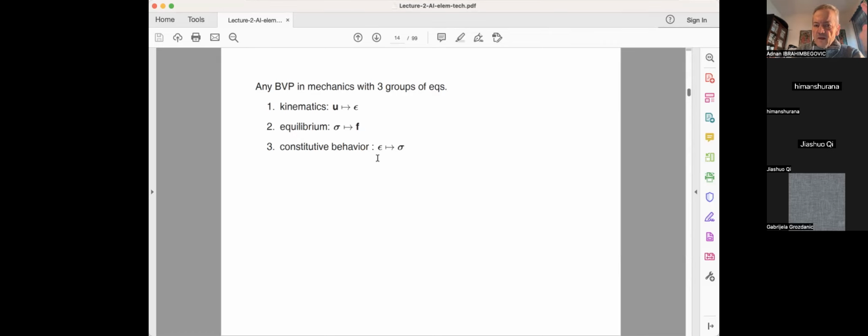So you can either go ignoring the symmetry of u, epsilon and sigma, which we do nowadays in some interpolations which are very useful for dynamics. Just one remark: the finite element method is the best discretization method when it comes to statics. It has the so-called best approximation property in the energy norm when it comes to an elliptic problem, like elasticity or the stationary case of heat transfer. But when it comes to non-stationary problems like dynamics or non-stationary heat transfer, that's not necessarily the case. So you need something better, some kind of interpolation which enforces continuity of stress or heat flux and things like that. And for that, you have to abandon the symmetry of the stress.